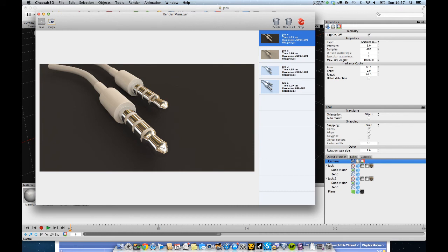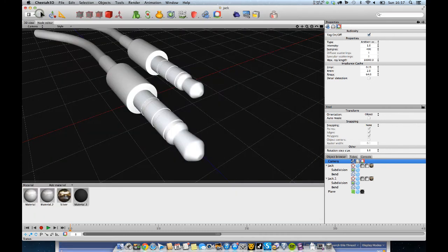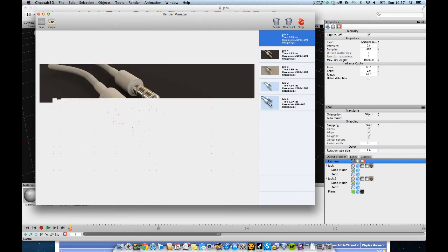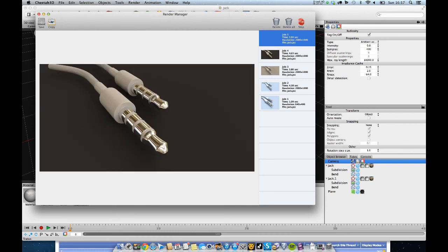I'm going to power down the ambient occlusion, I think. Try and depend a little bit more heavily on the light from the HDRI. Let's have a look. So let's power that ambient occlusion down to 0.8. Give that another render. Okay, we're getting there now.